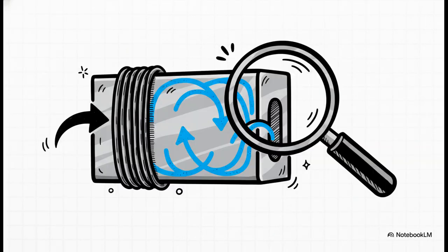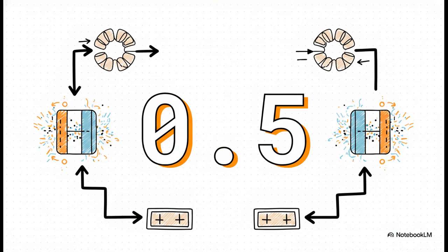So that brings us to inductance, our L. You can think of inductance as the perfect metric for our circuit's efficiency. Measured in henries, it basically bridges the gap between the electrical current we pump in and the magnetic flux linkage we actually get out of it. If we have a circuit with a huge air gap, that high reluctance means a much lower inductance. It's a direct, measurable value of how well your specific physical geometry, the core, the wires, the gap, creates a usable magnetic field.